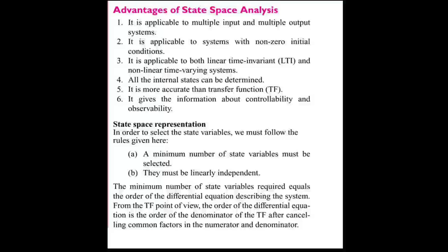Advantages of state space analysis. First, it is applicable to multiple input and multiple output systems. Second, it is applicable to systems with non-zero initial conditions. Third, it is applicable to both linear time invariant and non-linear time varying systems. Fourth, all the internal states can be determined. Fifth, it is more accurate than the transfer function. Sixth, it gives information about controllability and observability.